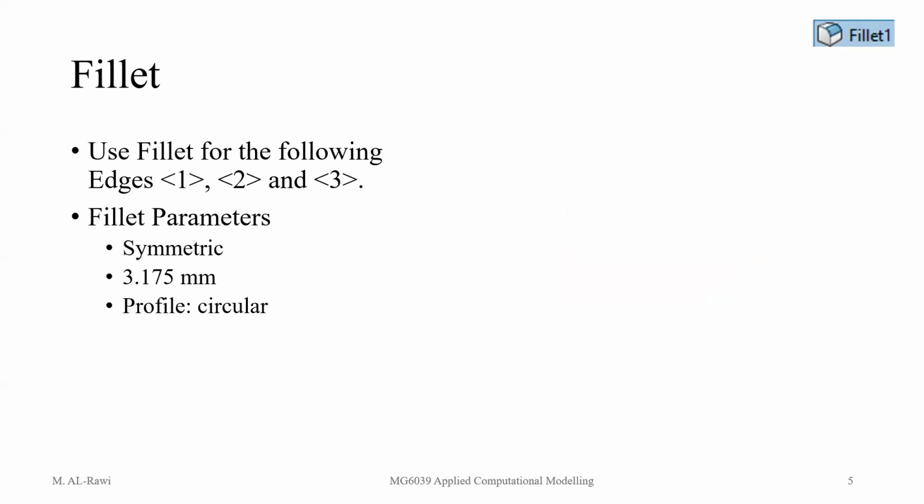Fillet. A fillet is used because instead of having those sharp edges, we want to convert them to rounded edges. So go to features, and under features, search for fillets. You find them right under the option where you find the shell. Where you find the shell components, there is a fillet. That's shell. Where do you click on shell?